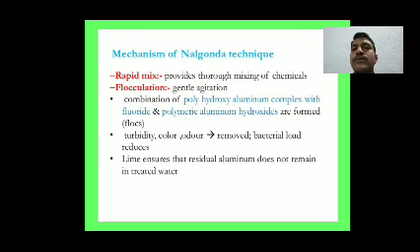In this technique, alum, lime and bleaching powder are added to the fluoride water, then mixed rapidly with each other, so the coagulant is uniformly dispersed in the single or multi-phase system.